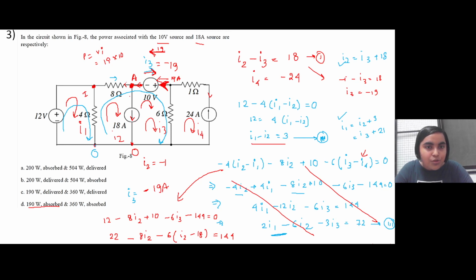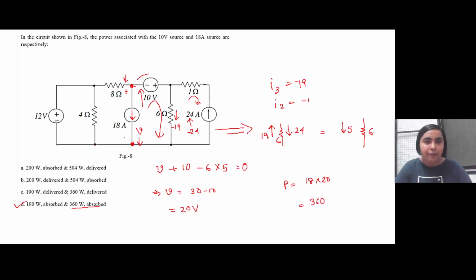So 18 ampere flows through this particular one. Why do we consider I3 only for this? Yeah, look into this. From A to B, across this branch, this voltage source is connected. It is not connected across, let's say, O, A, B. It is only connected across A and B. And at this A, another resistance comes up. So we cannot independently say that BA to O is a single loop. Node A is again connected to this 8 ohm resistance, right?